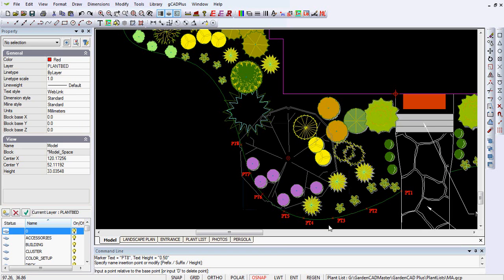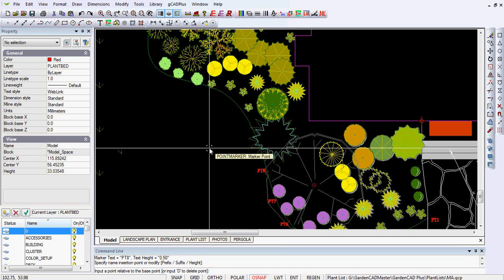Construction teams often find it quite difficult to lay out the edge of garden beds. You can see this green line moving around here is quite a complex shape. And we give you a tool that is found on the Tools drop-down menu that enables you to set it to first indicate a set-out point, and I've done that at a convenient point where the landing of the steps meets the house. And then I can set points at reasonable intervals, and where the radius of curvature is changing quickly, I put more points in and work my way around the edge of the new garden bed.